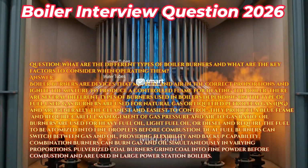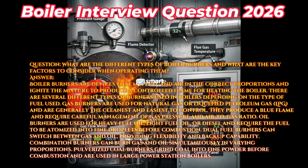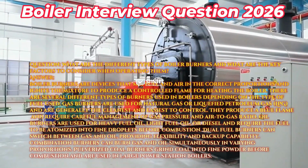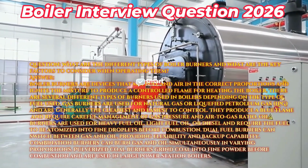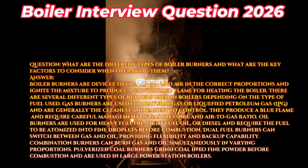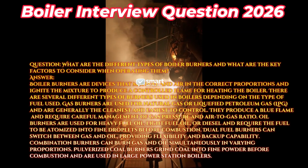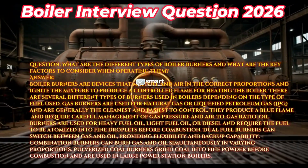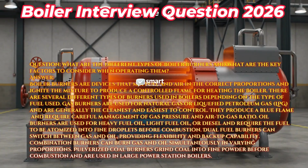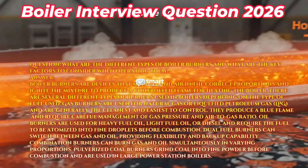There are several different types of burners used in boilers depending on the type of fuel used. Gas burners are used for natural gas or liquefied petroleum gas, LPG, and are generally the cleanest and easiest to control. They produce a blue flame and require careful management of gas pressure and air-to-gas ratio. Oil burners are used for heavy fuel oil, light fuel oil, or diesel and require the fuel to be atomized into fine droplets before combustion.